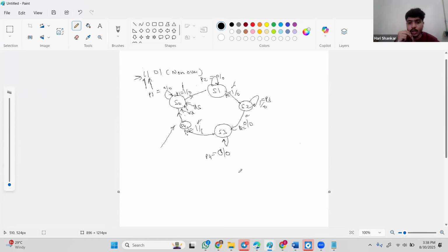It does not depend solely on present state. So in Mealy overlapping, S4 can directly go to S1. The explanation before was for Moore actually. So for Mealy FSM, it will be only n states, but for Moore FSM, it will be n plus one states if we consider n bits.